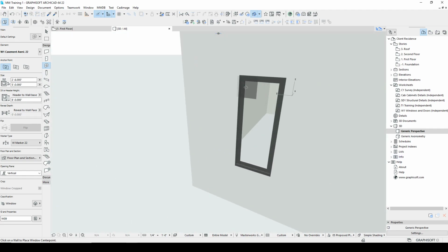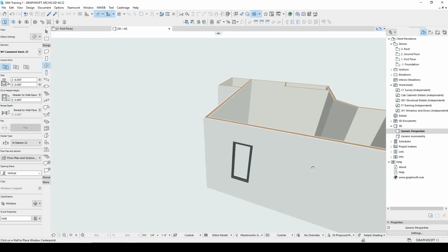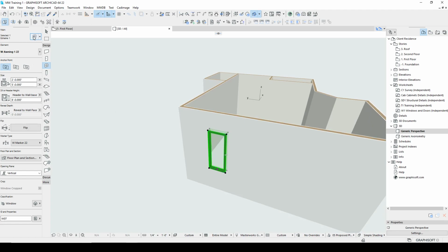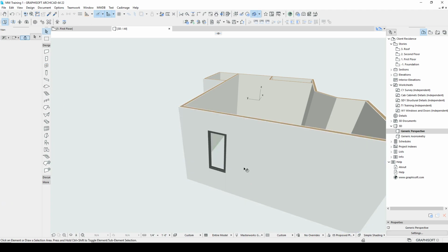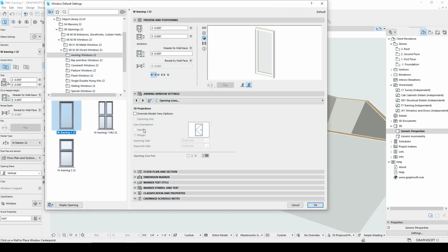You can see here I have the exterior material, the interior material. This is an awning window, 2x5. Here's my node. Now, if I want to take these properties, this is an important strategy here. I use Alt, I pick up those properties. That goes into my awning. I can copy the properties from one window type to another type, and that can become very useful.